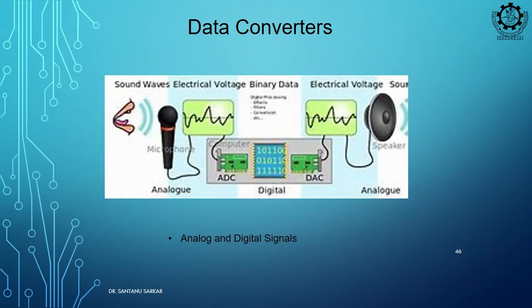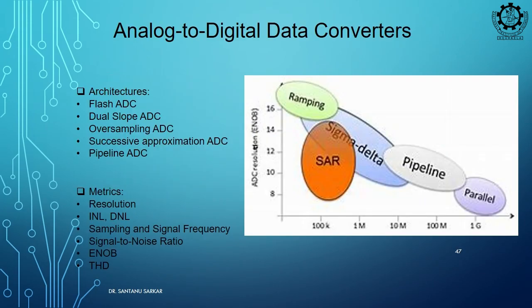Okay. A few examples are data converters in your audio codec, audio amplifiers, and different architectures. So, we discussed the selection of architecture. You need to choose based on what your application is, what your specifications are, in which frequency you will be operating, and for that frequency which architecture is more suitable.